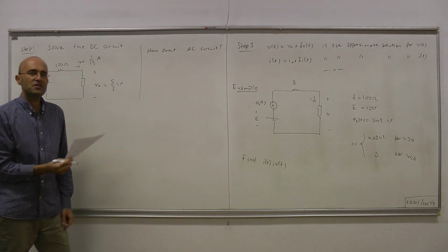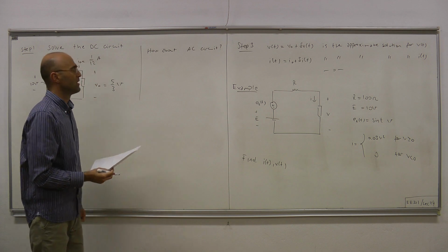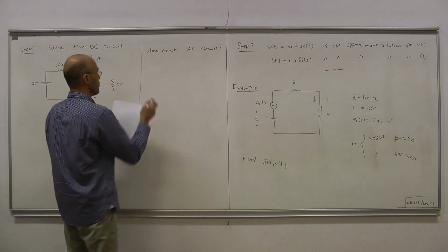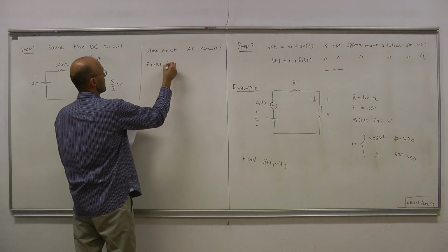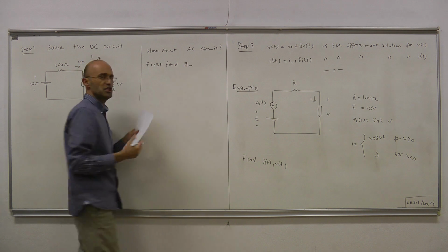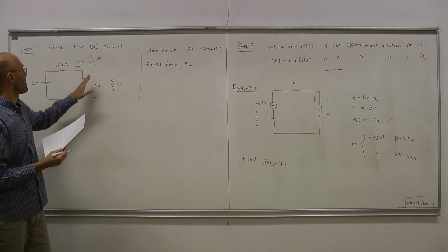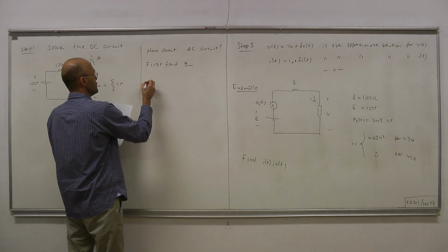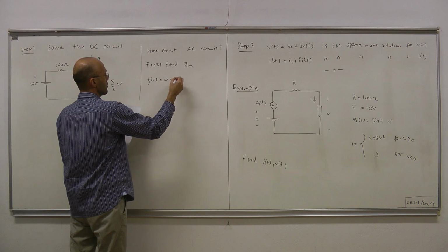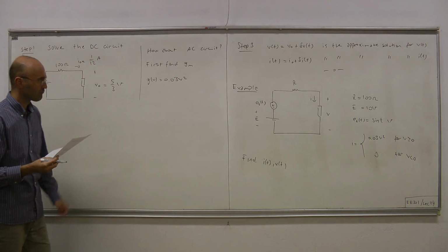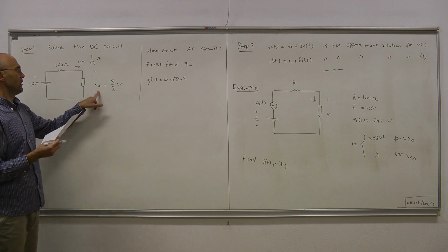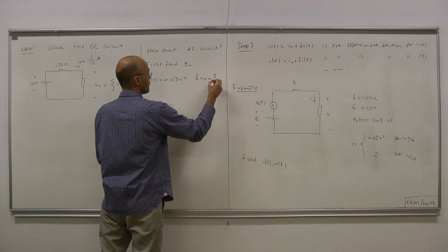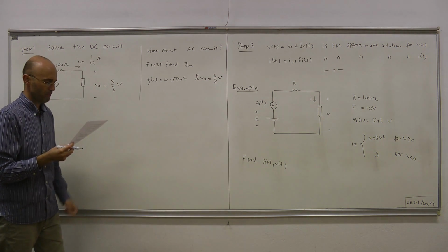Okay. For that, all we need is the resistance of the resistor that will represent the nonlinear component. First, find Gm, the slope of the curve i equals g(v) at the DC operating point. Now, g(v) is 0.03 v squared, because the voltage is positive, and V0 is 5/3 volts.